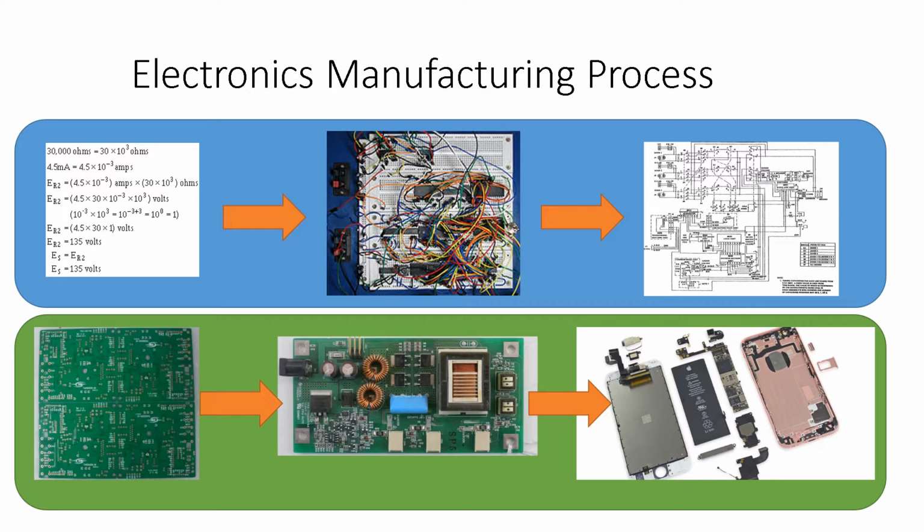So these parts come from the schematic. You don't get to pick them. However, you do have to make sure that all these parts fit. If you put two inductors real close to each other, they might not fit on the board and you're going to have problems. Or if you're trying to build something thin like an iPhone, you're going to have to make sure that all your parts have a very clean and small form factor. So you might change companies for some parts in order to make sure they fit on the board.